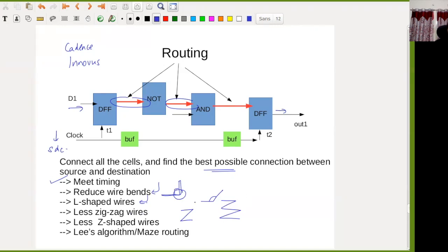In addition to just these, there are several other guidelines such as the width of the wire, the spacing between the wires, and what is the amount of crosstalk it would induce on each other. So all of this is part of what is called signal integrity. So to maintain the quality of the signal from the source to the destination. So usually there will be losses. So it's expected that the signal goes through several losses along the path to the destination.